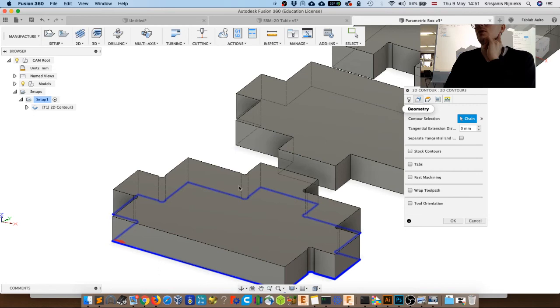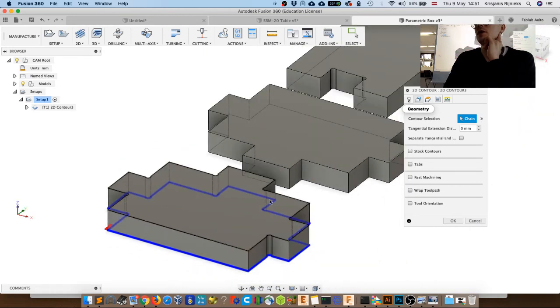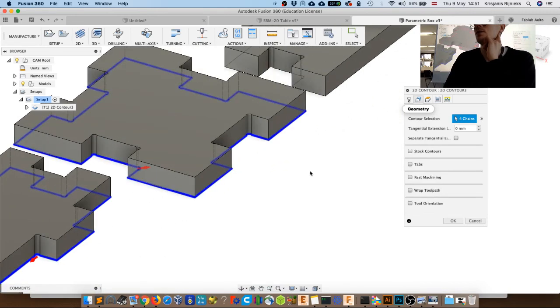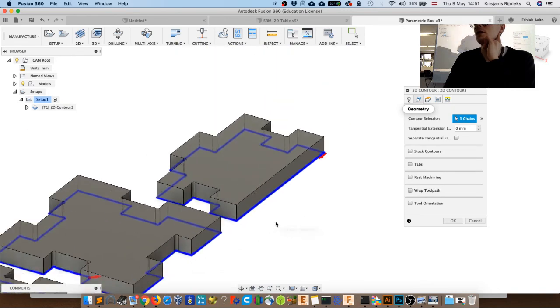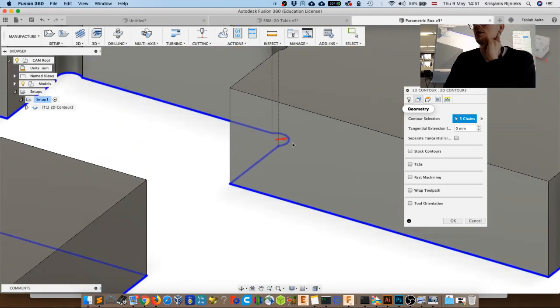So you wouldn't use the actual part. But we need this arrow to be outside, so the actual part that we cut out is precise and usable. Let's select the other ones, like so. By default, it's putting this arrow on the outside, except here as well.